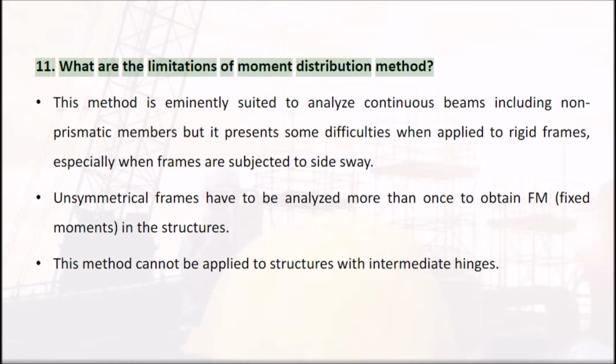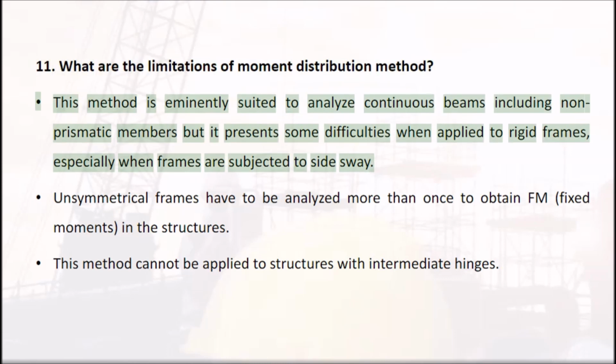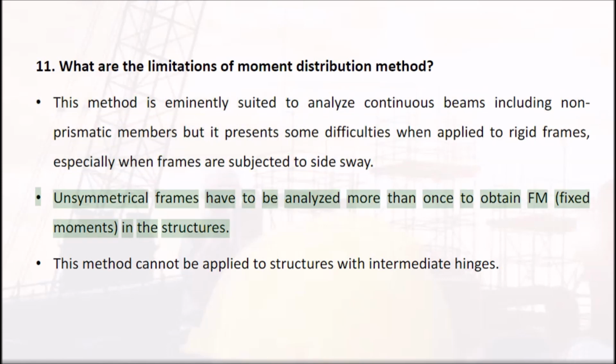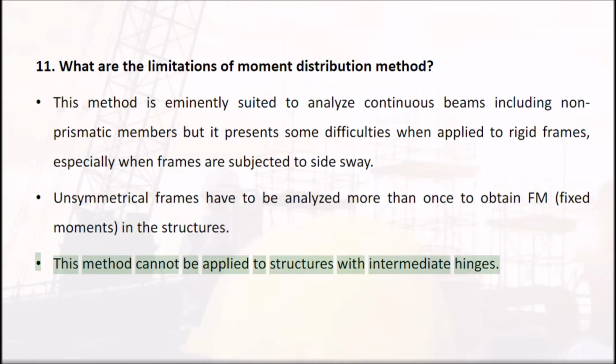What are the limitations of the moment distribution method? This method is eminently suited to analyze continuous beams including non-prismatic members, but it presents some difficulties when applied to rigid frames, especially when frames are subjected to side sway. Unsymmetrical frames have to be analyzed more than once to obtain FM, fixed moments, in the structures. This method cannot be applied to structures with intermediate hinges.